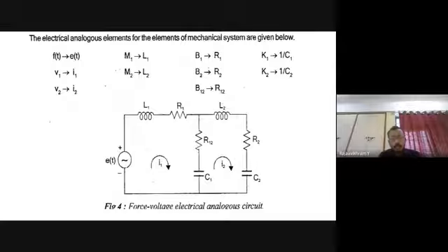So, remember the circuit. Now we are applying the Kirchhoff law to derive the equations. The first equation, which is the first diagram, represents the M1 node, and the second diagram represents the M2 node. We have to derive the electrical equation by applying the Kirchhoff law. For the M1 node, there is the input. For the second one, M2, the input is 0.